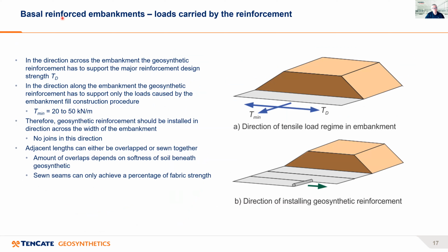Now, what we've done so far in the analysis of these basal reinforced embankments is we've analysed the load carried in the basal reinforcement in this direction, across the width of the embankment. And this is the design strength, TD, across the width. Now, there's also loads in the reinforcement in the longitudinal direction, but these types of loads are fairly minimal.